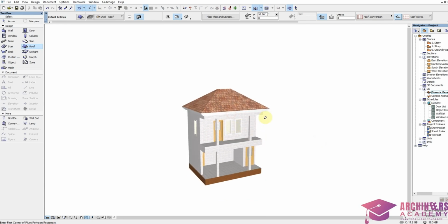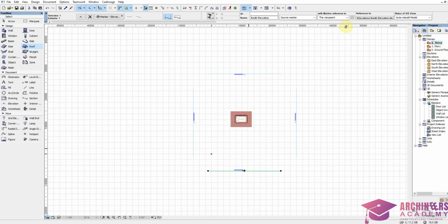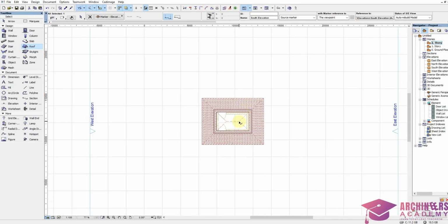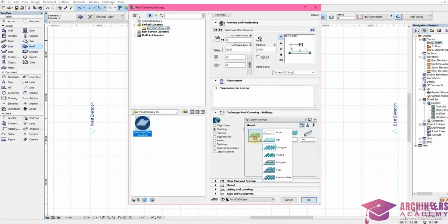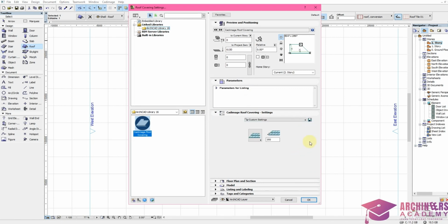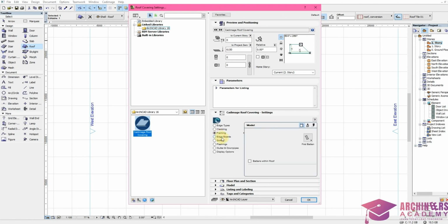Then if you have CAD image in your system, you can apply CAD image effect on your roofing, just like you can see in the perspective. Click on CAD image, coverings, roof coverings, then change this to be shingles, increase the width to 35. Come over to frame, cladding, headboards, soffits. Then at flashing, you change this to maybe square rib. Gutter 2, you can change this to maybe colonial and this to external.